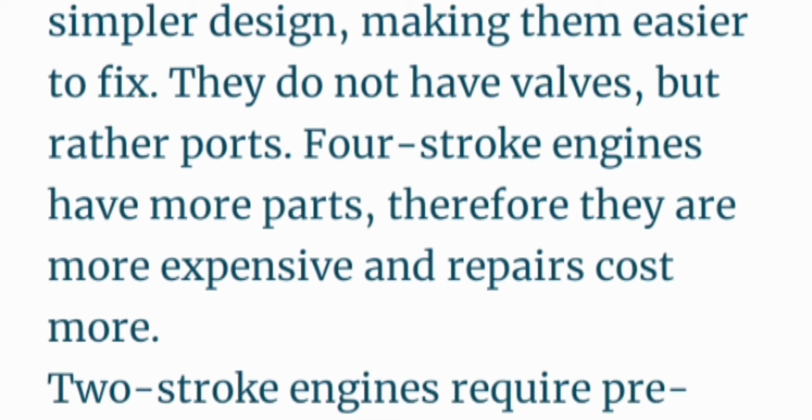That being said, two-stroke engines are more powerful. Two-stroke engines are a much simpler design, making them easier to fix. They do not have valves but rather ports. Four-stroke engines have more parts, therefore they are more expensive. Two-stroke engines require premixing oil and fuel, while the four-stroke do not. Four-stroke engines are more fuel friendly.